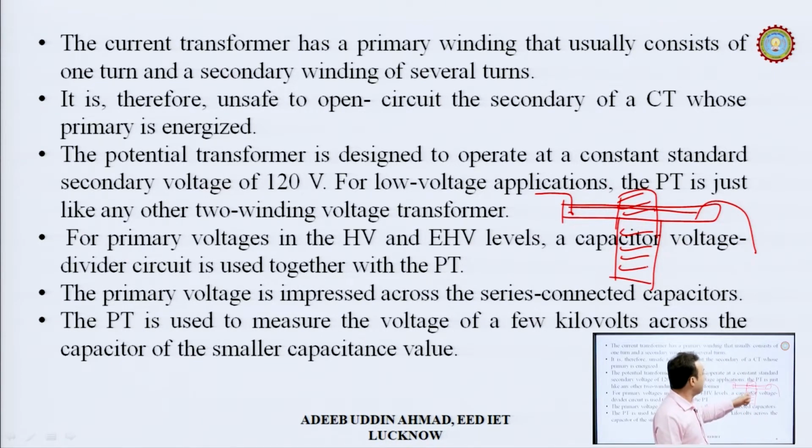That is a safety procedure. We are not going to open the secondary when the primary is energized. The secondary is always closed because of the safety parameters.